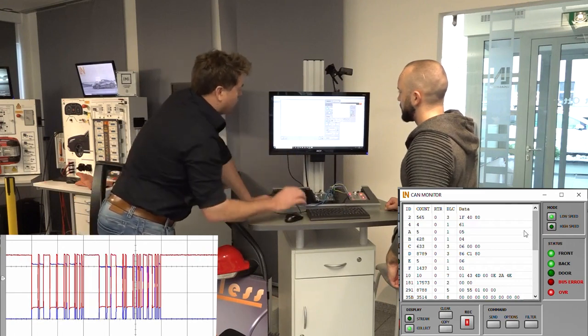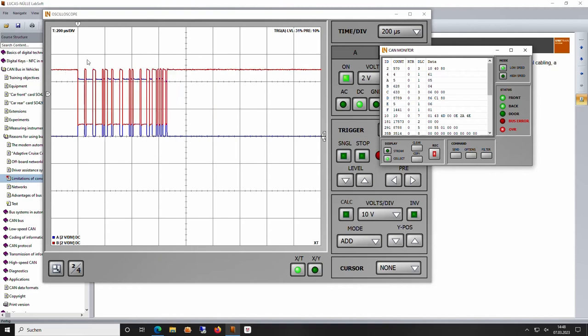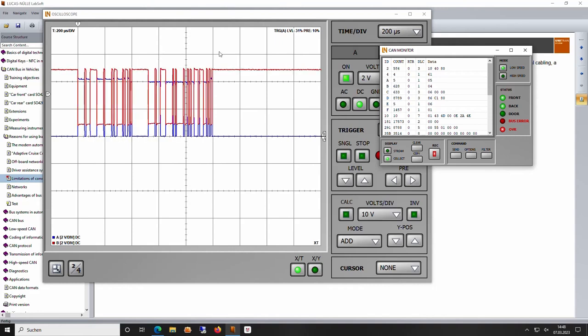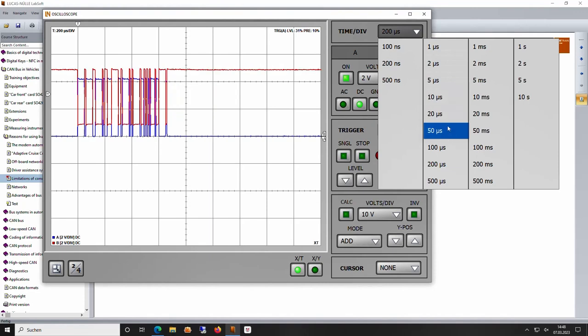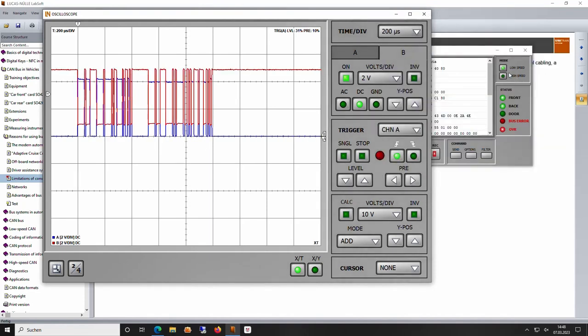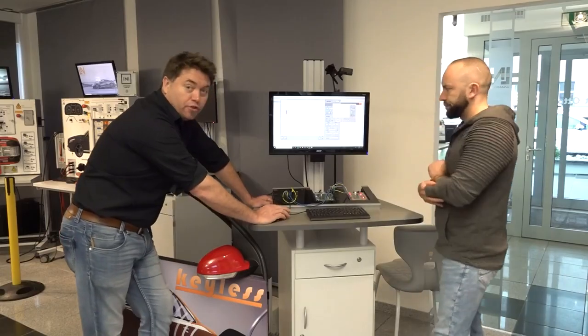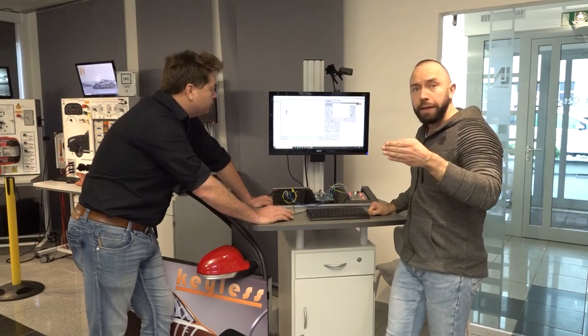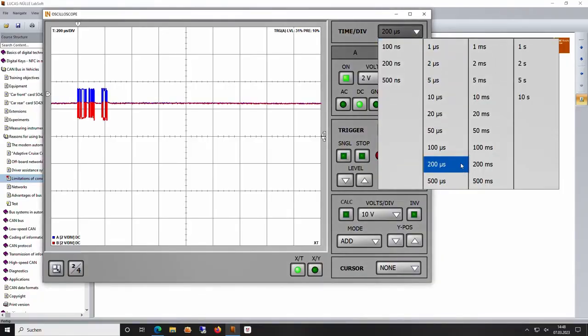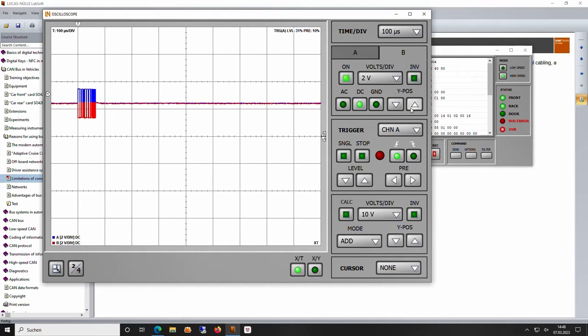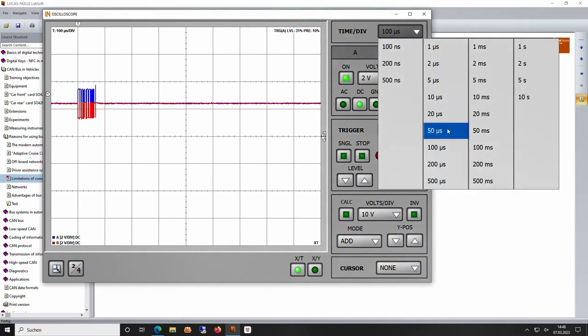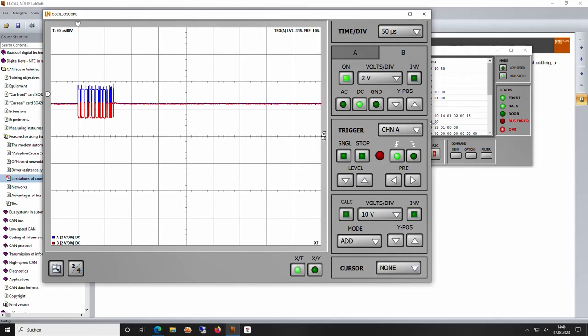And so we can even work out what the time frame is for a message. So this is 200 microseconds. So 200, 400, about 600. Something like that, yeah. For a message. 600, 800. If we change it then to high speed, all of a sudden it's within less than 100 microseconds. So what does it mean? That means, just spoken pretty easily, that in a shorter time frame you can transmit the same amount of data. So of course that increases the speed of the system.